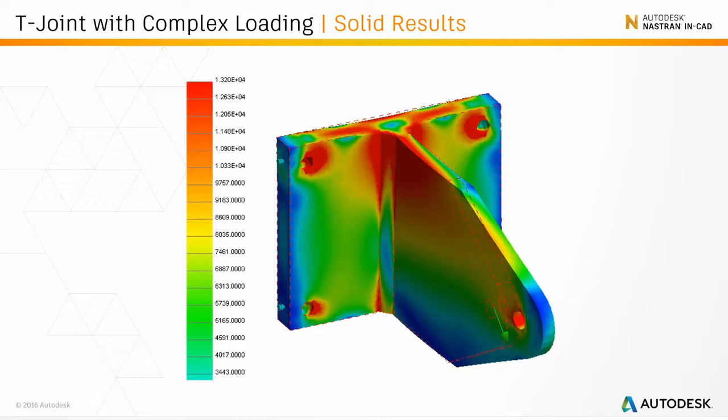The max legend on the left-hand side has been set to be the tensile strength of the weld electrode, so it's the yield or tensile strength of the electrode material. It's clear to see that the stresses are dominated by areas where sharp edges are present, like those on the chamfer, suggesting singularities. The stresses are spread out into the face of the weld, so how realistic is this?